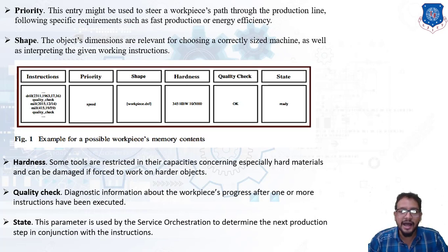So if the hardness is higher with respect to that workpiece, we need to change the tool, right? Tungsten carbide tool, right? So different types of tools are available. Diamond tip tool. So these tools can be utilized based on the hardness of a workpiece and can be modified.